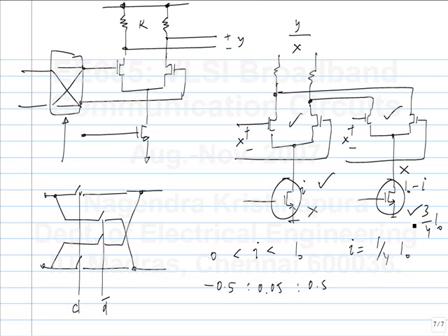We have already seen how to make a variable current source in digital steps. So, you use one of those methods to make this current source parallel, but then the digital control you provide to each of them, you arrange it such that the variation is complementary. If one of them is I, the other one is I naught minus I. Is this clear? So that's how some of the taps you may have to realize both positive and negative values, and this is what you have to do.